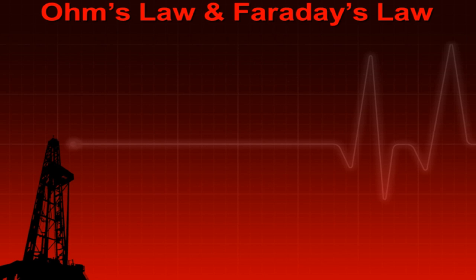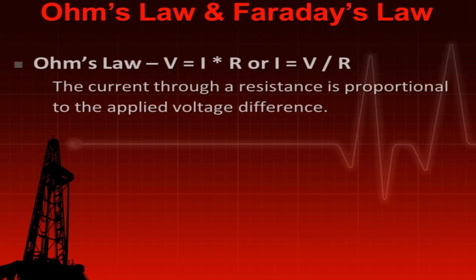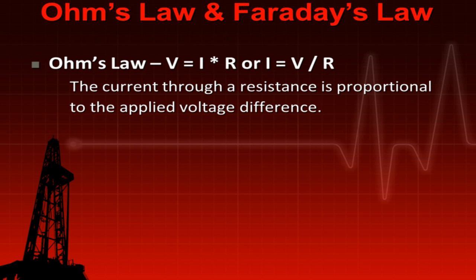Ohm's law, one of my favorite. Ohm's law and Faraday's law. So Ohm's law is very simple. It just says the current through a resistance is linearly proportional to the applied voltage difference. So if this phone is 10 ohms and I have 10 volts across it, I'm going to have an amp flowing through my phone. Okay? If the resistance of this phone is 1 ohm and I have 10 volts, I'm going to have 10 amps flowing through this phone.